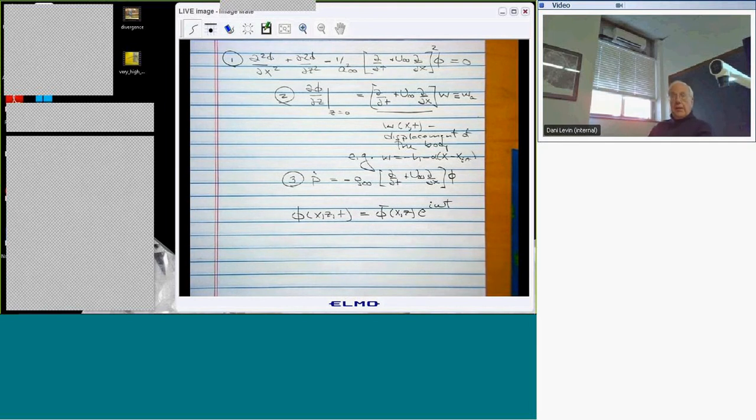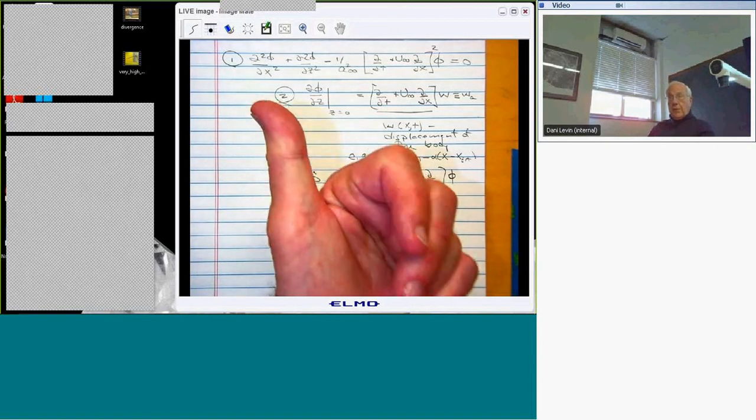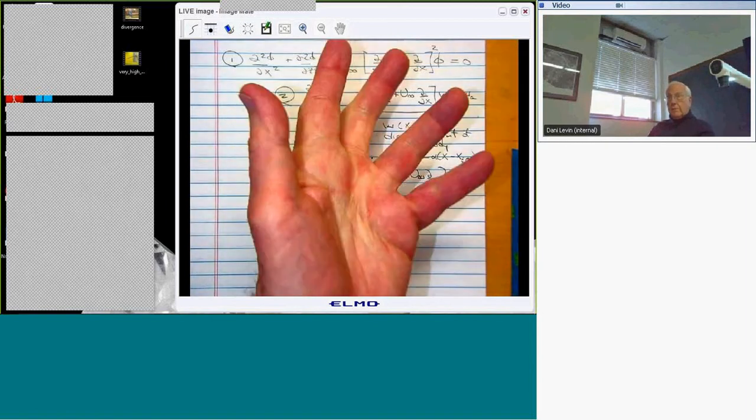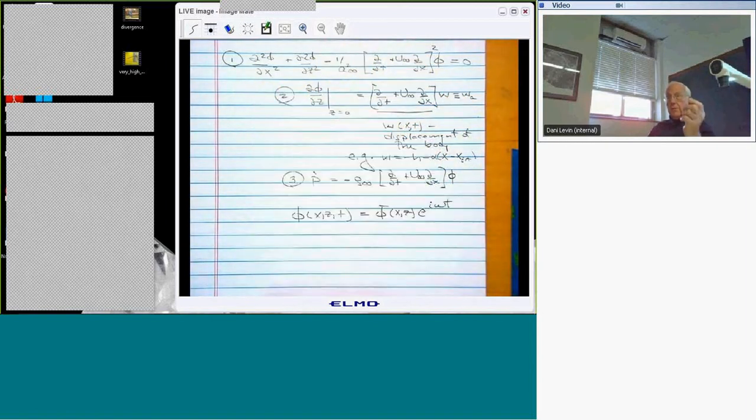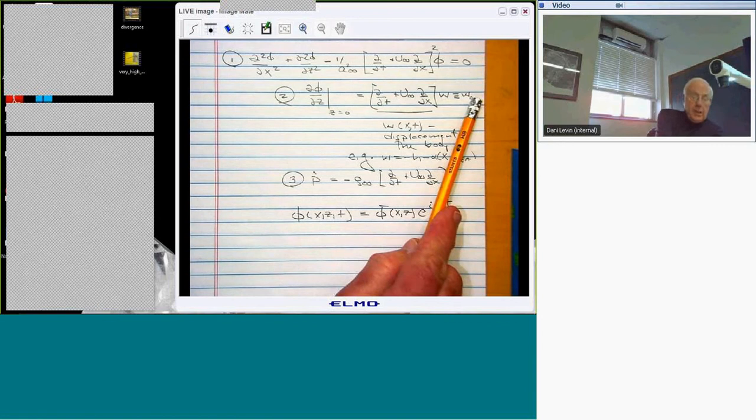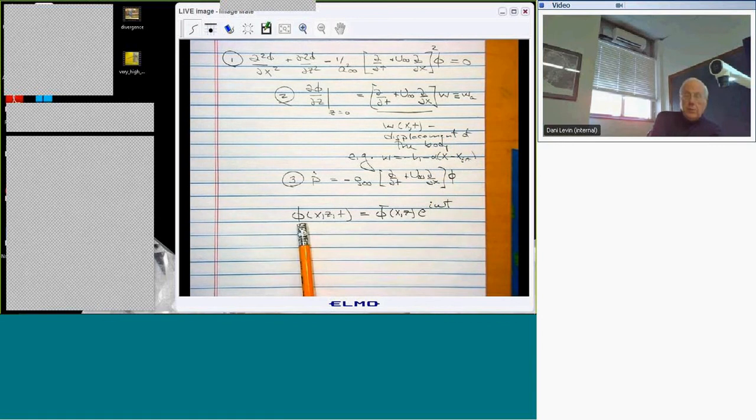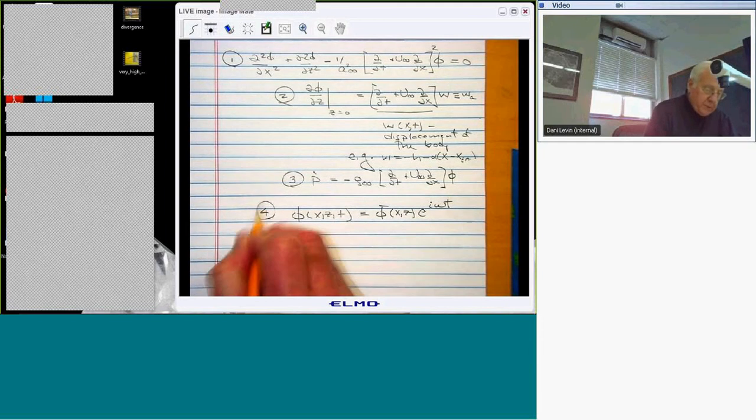And then again, you heard about random vibrations. Remember, if you have the transfer function, the transfer function comes from looking at sinusoidal motion. So there's an aerodynamic transfer function between W sub A and phi, for example, or W sub A and pressure, right? There's a transfer function which we effectively can compute by solving this problem. Okay, so we're going to do that. We'll call that equation 4.